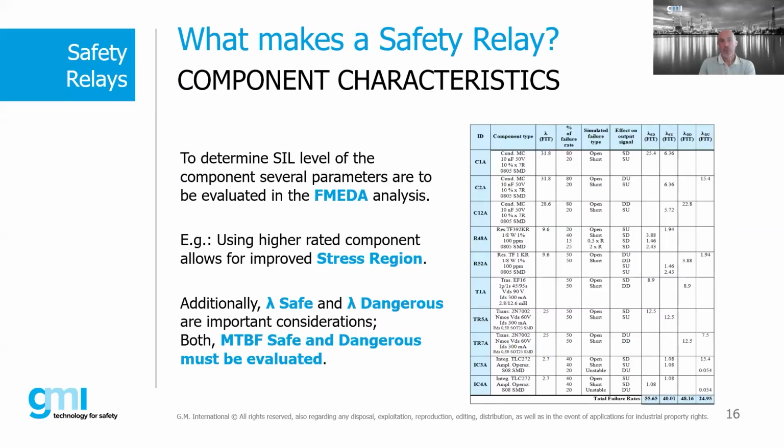Okay, so indeed, but there are a few things to keep in mind. For determining a SIL level of components of a system or modules like our relays, they have to, of course, evaluate the FMEDA for each component.